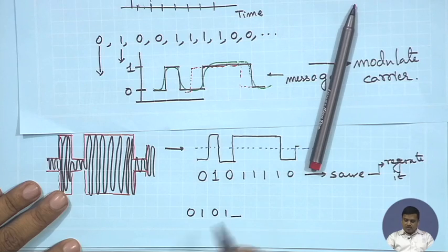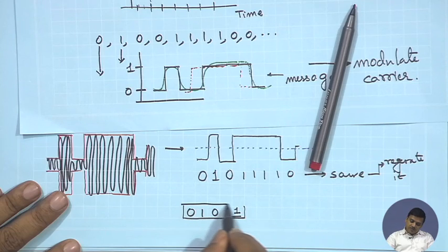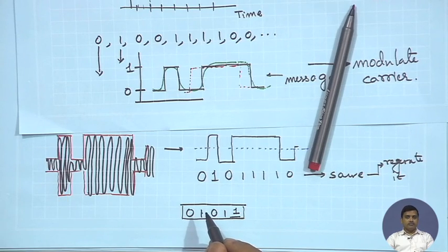When I say I want to have an odd parity, I am going to have one extra bit over here, which will be used to complete the parity to make it odd parity. So, as of now I have 2 1s. If I put one more 1, I am going to get 3 1s. So, I will know whenever I receive 5 bits, 1, 2, 3, 4, 5, the sum of 1s should be odd.